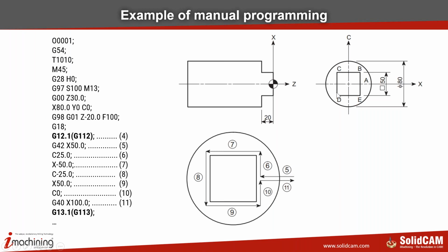First, here we have a simple square of 50 that we want to achieve, and the tool just goes within these lines. It is nothing so important. Here we have the tool call. We'll go to the milling mode. Then we will go to C-axis 0. And it is very important for me to mention that you need to go to C0, but not truly. I will also talk about that later. Then we will turn on the live tool. We will approach first in Z. Then we'll go with X, Y, and C.